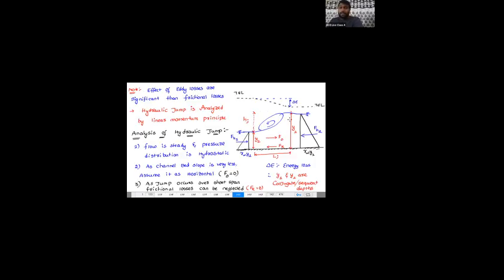Okay. So now, my dear, when the hydraulic jump is going to happen, keep that in your mind. Whatever the height of the jump, that depends upon the difference between y1 and y2, and the length of the jump depends upon the height of jump, which in turn depends upon y1 and y2. So we need to analyze this y1 and y2, and why I am calling this conjugate or sequent depths, wait for a moment, I am going to discuss that.